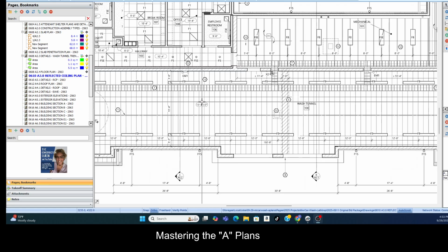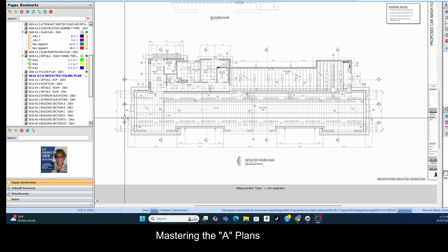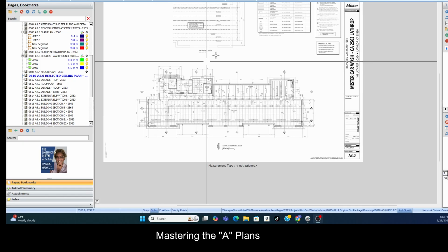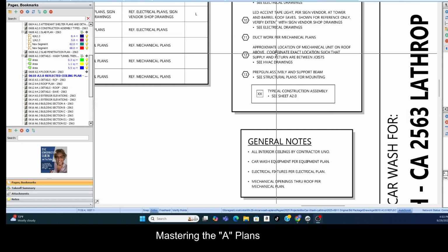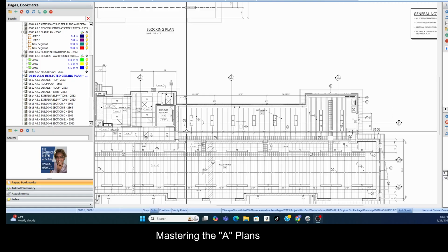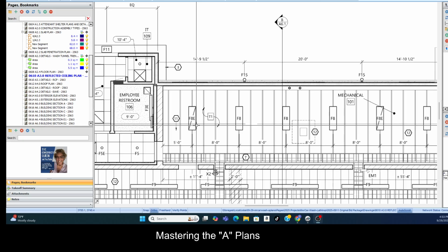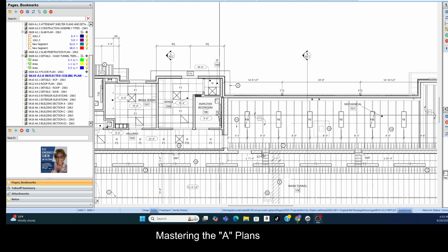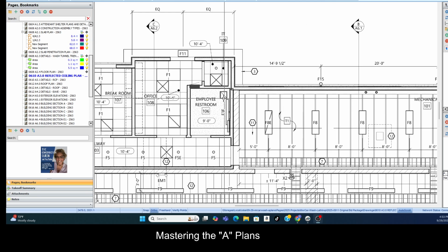Okay, so the reflective ceiling plan reflects, shows everything in the ceiling. And of course, you're going to go by your keynotes, whatever your keynote tells you. Okay, and you're going to make sure you have it there. But again, why is everything in there? Because each of the trades needs to know, the painter, how much of this is getting painted. Oh, okay, this much. I can go to the reflective ceiling plan and I can measure that out.